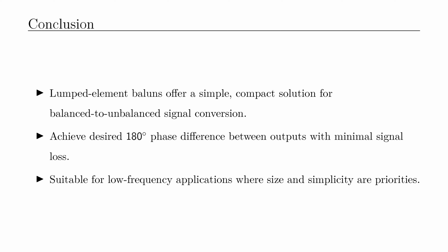In conclusion, lumped element baluns offer a compact and simple solution for converting signals between balanced and unbalanced formats. They achieve the desired 180-degree phase difference between outputs with minimal signal loss. These baluns are best suited for low-frequency applications where size and simplicity are critical design priorities.